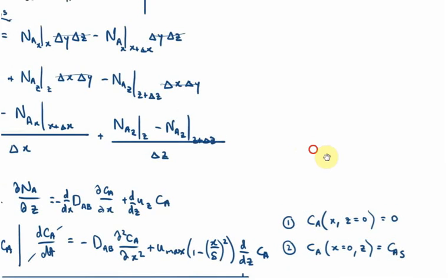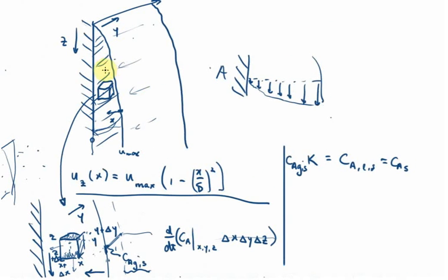Then for the third boundary condition, we can look inside this film and imagine what happens right here. So we've so far got what's happening at the top up here. We've also got what's happening on the surface of the film. And then if we look right through the film near the wall there, we can imagine that if this wall is not allowing component A to diffuse through it, right? If this wall is impermeable to component A's diffusion, then A might accumulate near the wall until it reaches some value, and then it's not going to diffuse in anymore. So it's going to look like this.